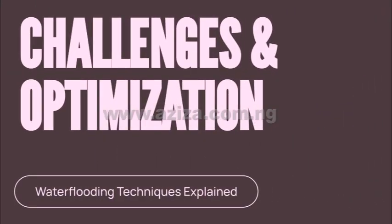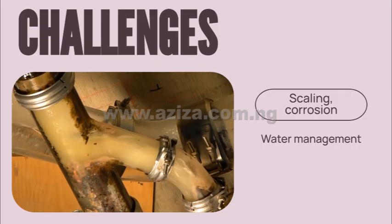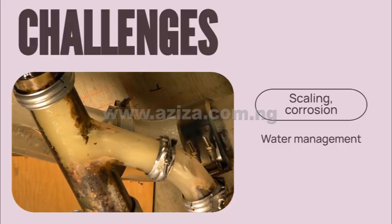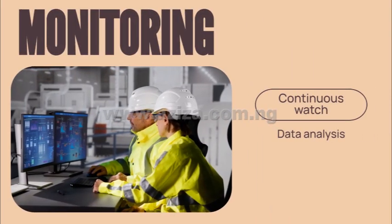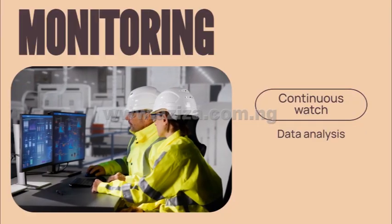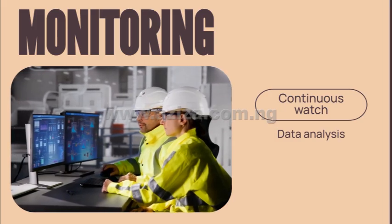Despite its effectiveness, water flooding presents several challenges that need to be addressed for optimal performance. Premature water breakthrough can lead to high water production and reduced oil recovery. Scaling, the deposition of mineral precipitates, and corrosion of equipment are common issues that require careful management through water treatment and material selection. Continuous monitoring and surveillance are vital for optimizing water flood performance. This involves analyzing production data, regularly checking well performance, and utilizing advanced reservoir simulation models to predict and adjust operations.